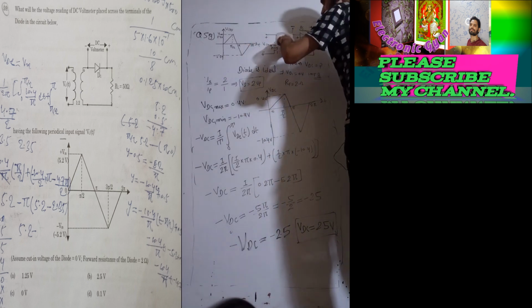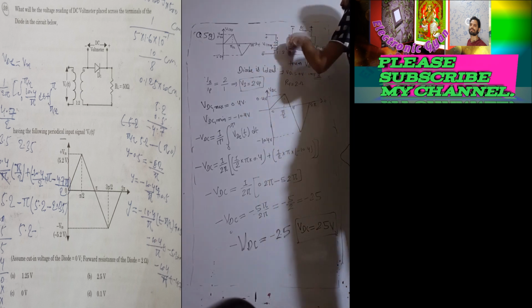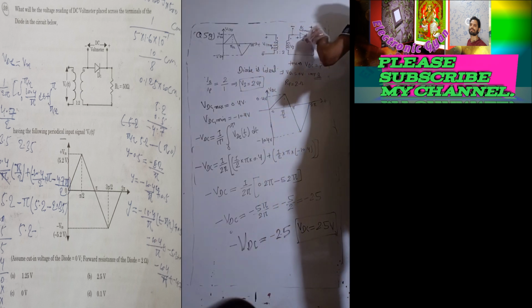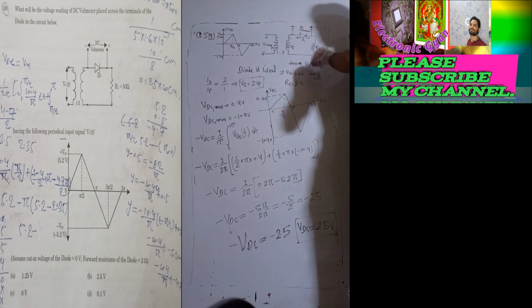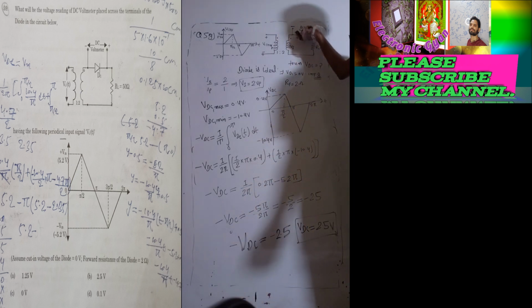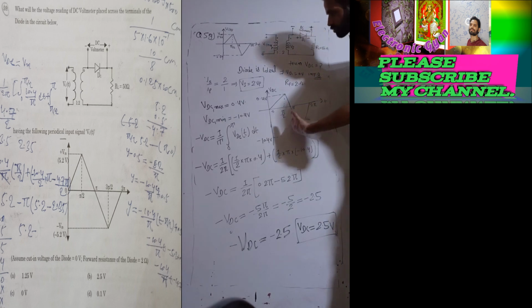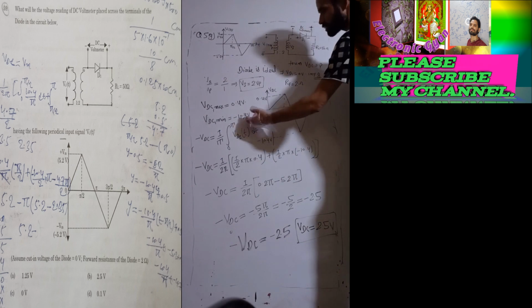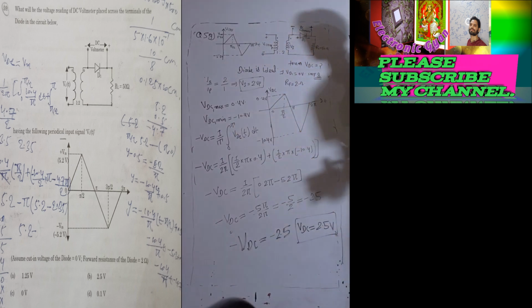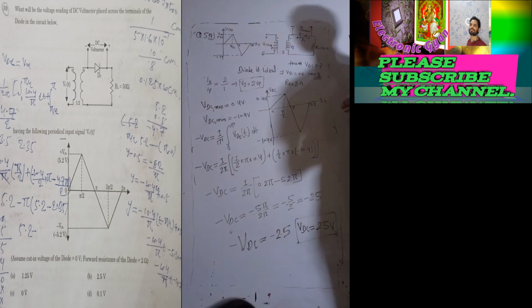So therefore, whatever the voltage across the secondary, the whole voltage will appear across this diode, across this DC terminal, because the diode is off and no current will flow through the load. So we get VDC1 minimum equal to minus 10.4. Okay, once we get this, what do we do next?